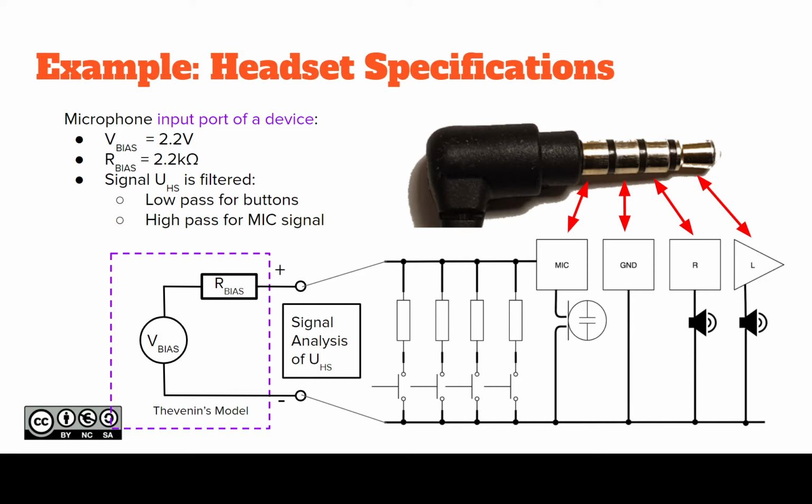One of those switches, I have only one, is the mute switch. When you press it, it just shorts that signal wire, meaning that you can detect, okay, 0 volts at input, meaning the mute button is pressed.